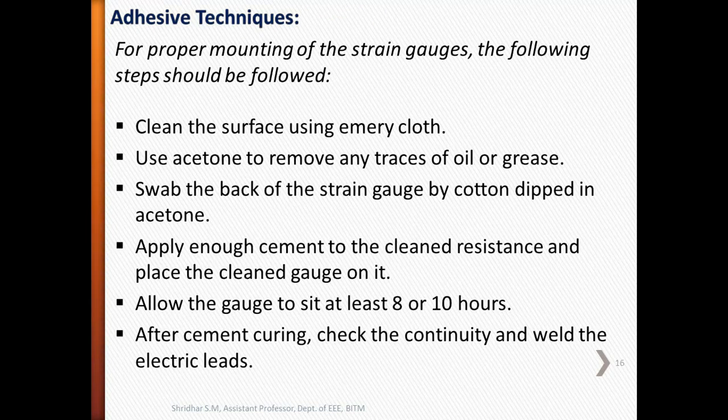Next, we'll discuss adhesive techniques. For proper mounting of strain gauges, the following steps should be followed. The first step: before mounting the strain gauge on a surface, the surface must preferably be cleaned by emery cloth and the base material exposed. Second step: remove various traces of oil or grease, etc. by using a solvent like acetone.